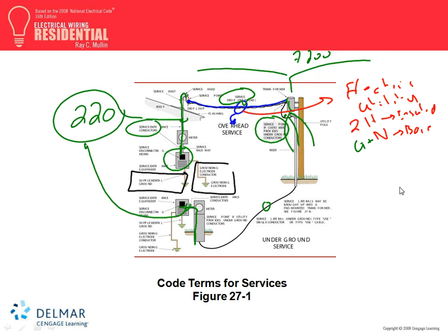That will be your grounding electrode conductor. And that's the one that we're going to be sizing based on what? You guys remember how we size these? These two? This is going to be Table 250.66. That's where your 250.66 cable comes in. So that's the one I want to bring up, guys, about the services.